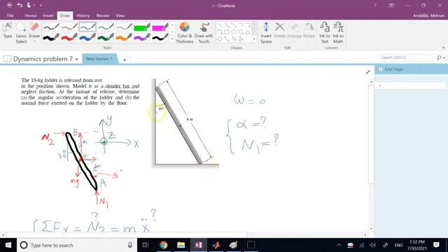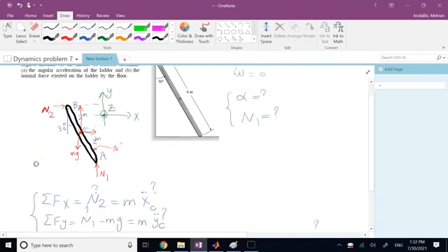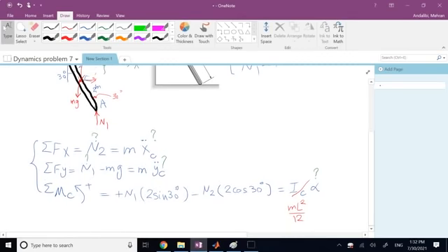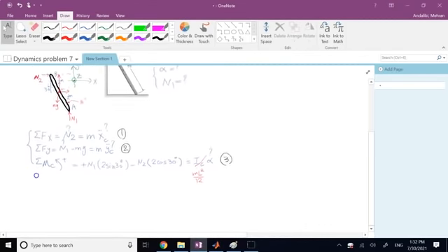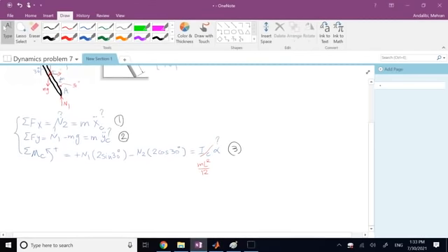So when you go, for example, like this, now, if you look at your centroid is here. So clearly your centroid does move along both x and y. So none of these components is 0. How much are they? We don't know. But clearly you see I have 5 unknowns, right? So if I number my equation 1, 2, 3, I have 5 unknowns, and I cannot solve for the 2 unknowns of this problem. And so kinetics cannot give me any more equation at this point.